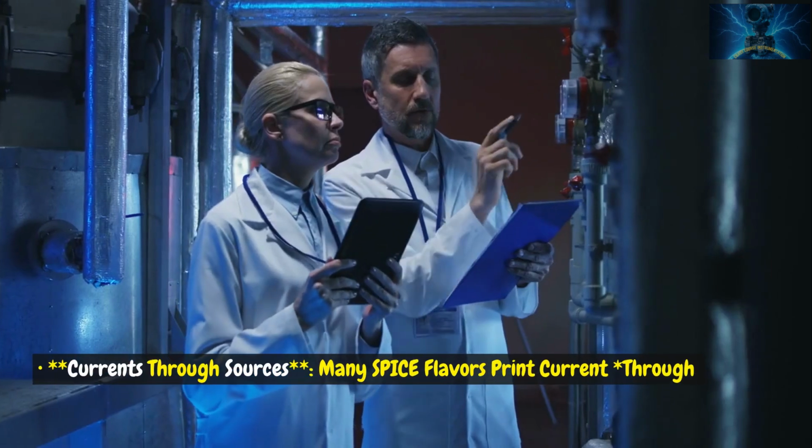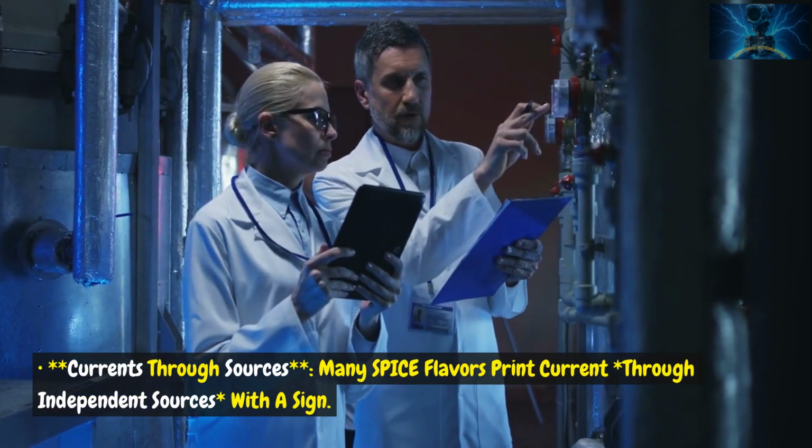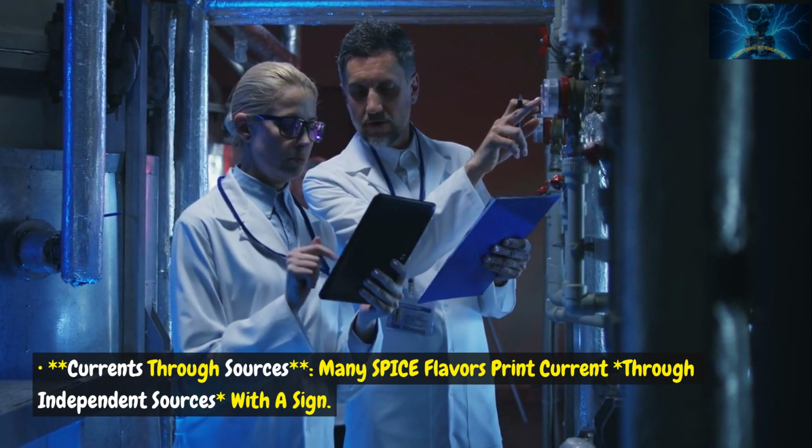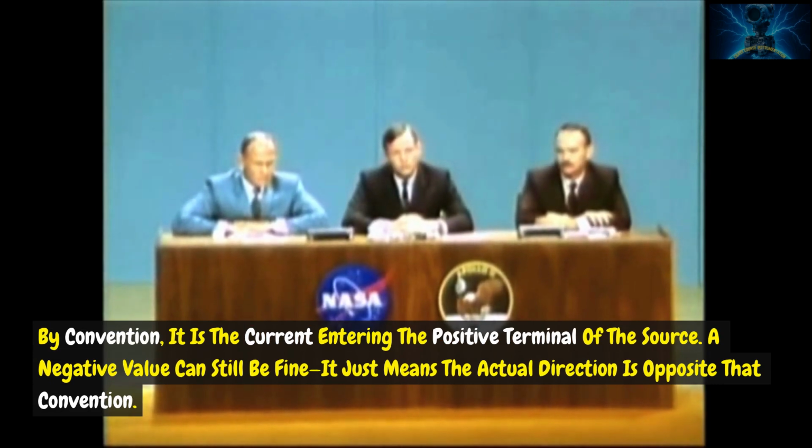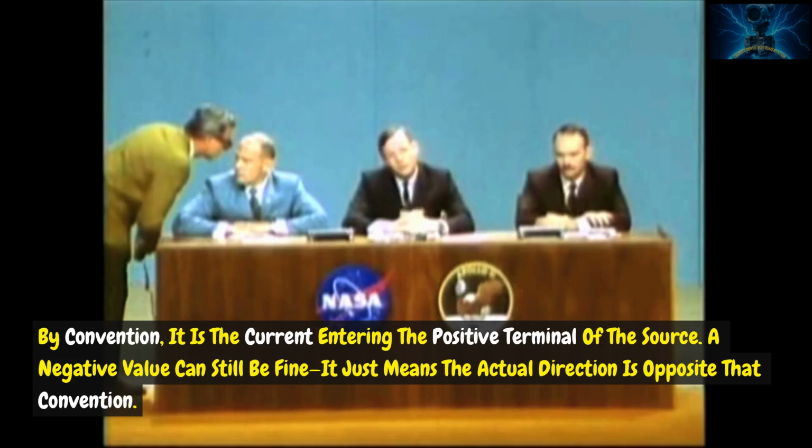And currents through sources. Many SPICE flavors print current through independent sources with a sign. By convention, it is the current entering the positive terminal of the source. A negative value can still be fine. It just means the actual direction is opposite that convention.